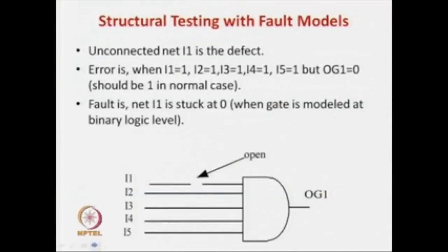So, if we can find a fault model which need not be the functionality of the gate, but can still serve the purpose of testing, then we have a very good fault model. A fault model reduces the complexity of representation, but at the same time you have to understand that it does the job or meets the specification for that particular context, which in this case is testing. We will take an example so you can understand better.